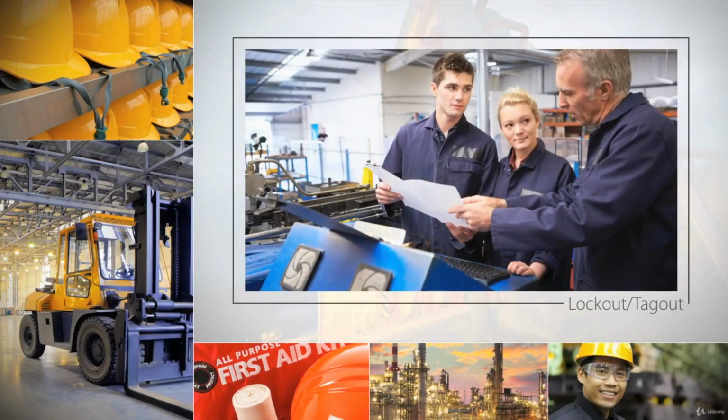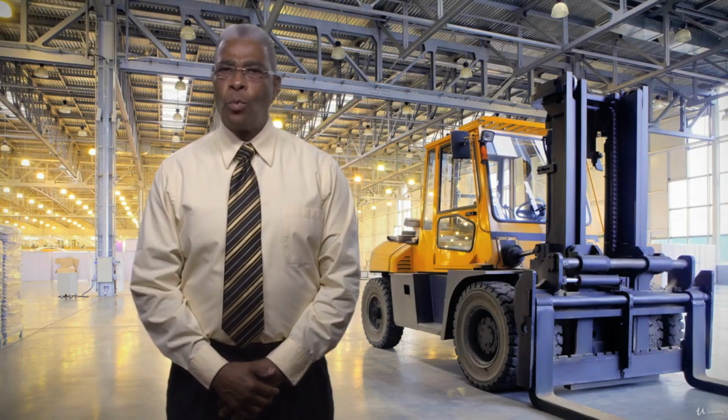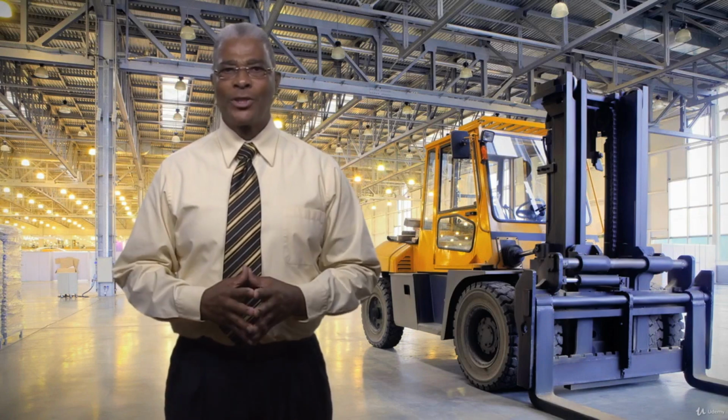The employer must document the lockout-tagout procedure. The procedure must contain the requirements to safeguard employees while they are working on or near de-energized circuits, parts, or equipment. Procedures must require pre-planning to determine where and how employees must disconnect electric energy sources to safely de-energize circuits and equipment.